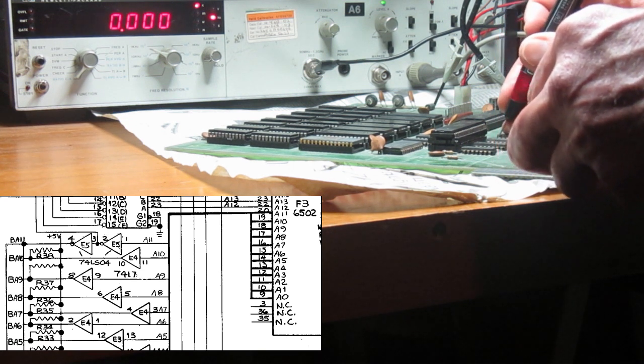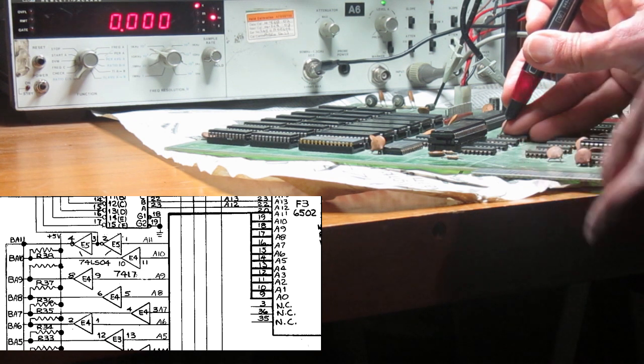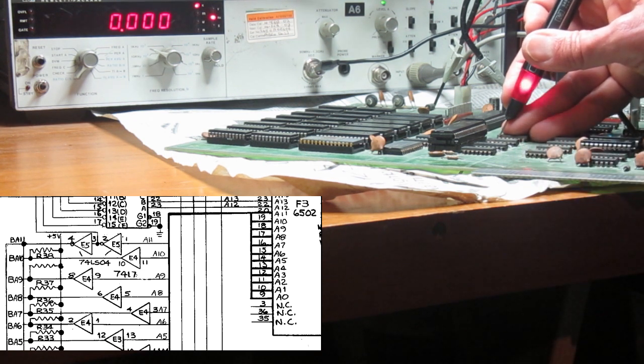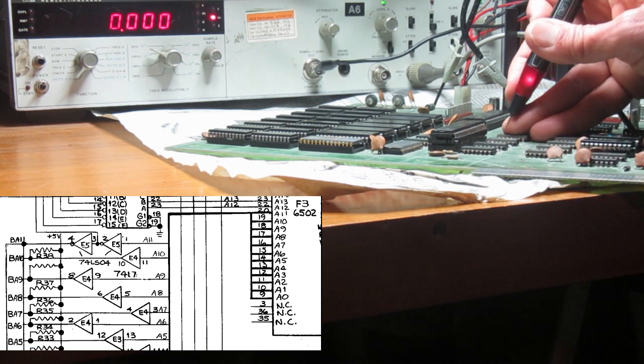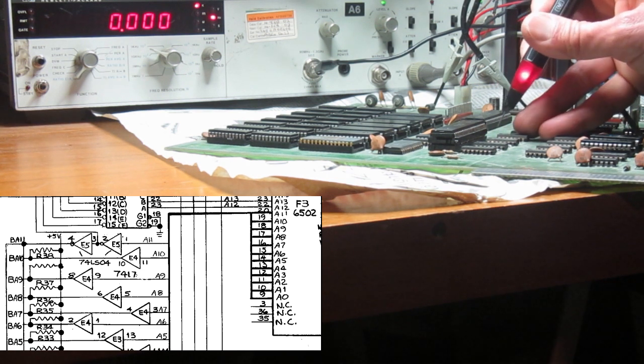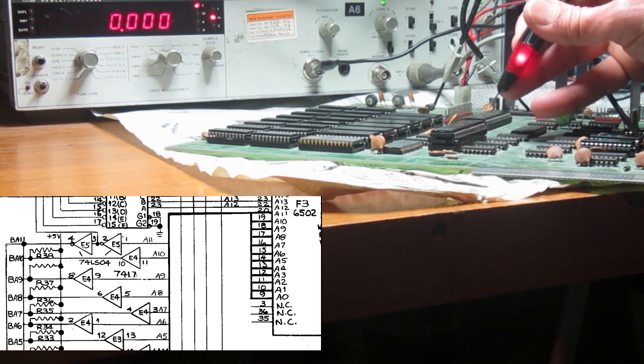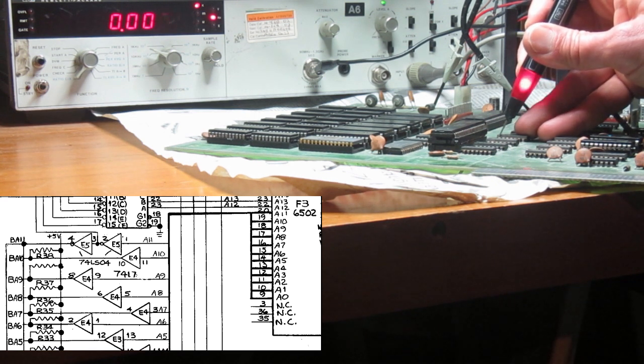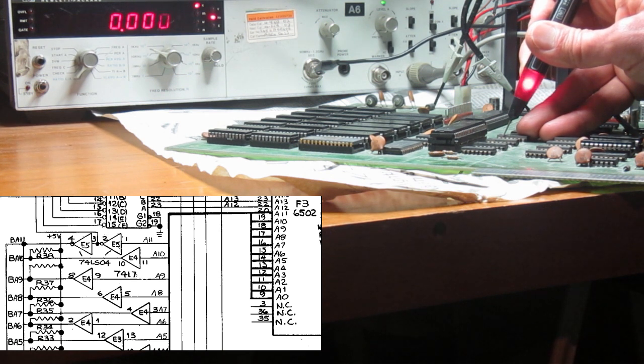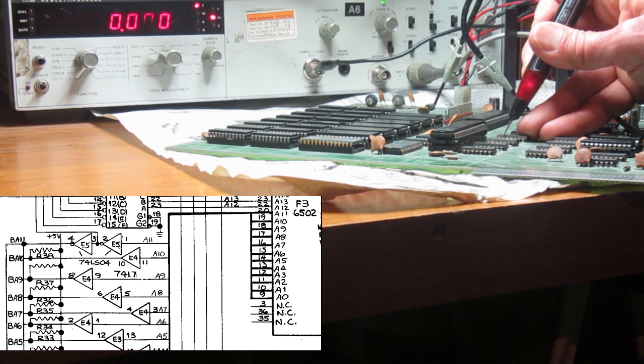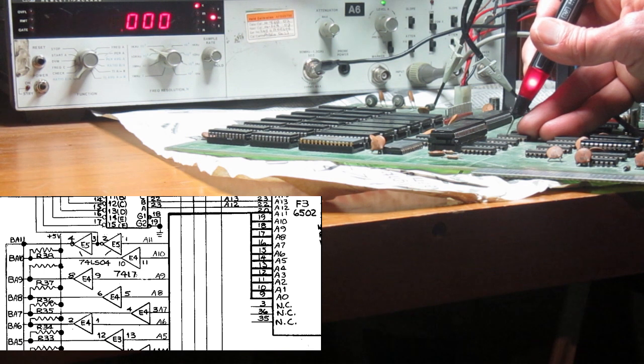So as you can see, the logic probe on pin 1 is toggling. So A11 then goes to pin 2 of the same chip. Oh, that's toggling because of my touching the probe with my finger, but yeah, okay, that's good. Pin 2 also works as expected, the buffer is working. Then it enters pin 3, again the same address, of course they are connected together, and exits on pin 4. So this buffer is working.